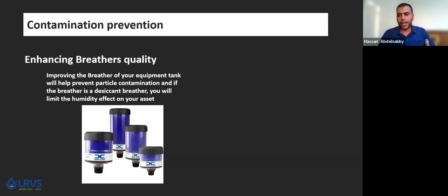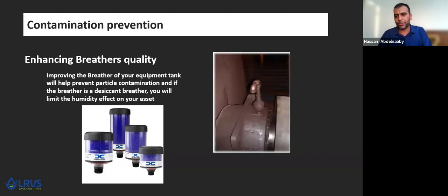But a piece of advice: if you see this kind of breather, you need to kill it at once and try to put in a better solution, because you are introducing humidity, you're introducing dust. Whatever the environment is, whatever is going to go inside your asset, you will spend much more money to remove it again from this asset.